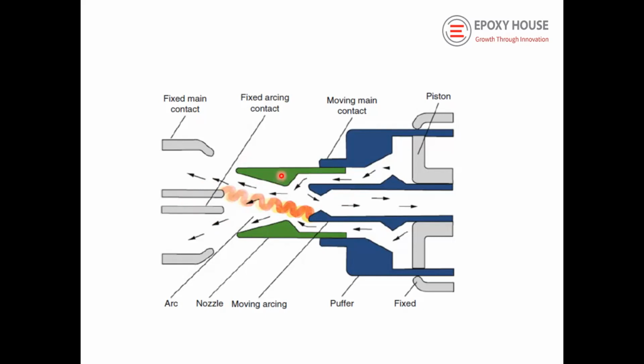To improve the performance of this PTFE, people are using different compositions, like boron and other materials, because erosion has to be reduced. When it operates, the temperature goes above 5000 Kelvin. That temperature easily erodes the surface and changes the shape, and this angle is very critical.